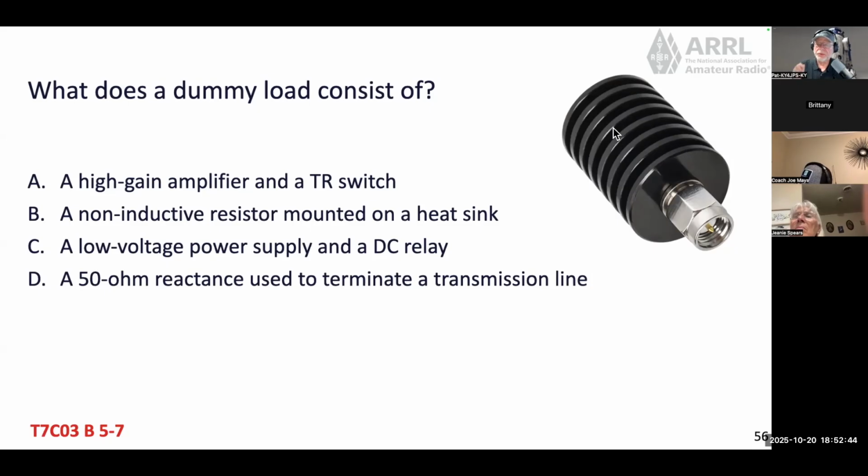So if you're transmitting a signal, you'd have your coax attached to this. And if you're transmitting and testing your radio, that resistor is going to heat up, and these metal discs would dissipate that heat out. It's kind of air cooled, like you would see on an air cooled motor. And that might get warm, but it keeps you from sending signals out and interfering with other radios.